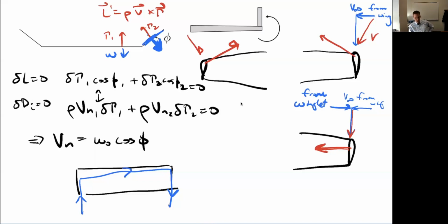So in other words, with this type of optimal loading, I've kind of increased the loading on the winglet such that it's not really getting any benefit, but it's generating more circulation that actually helps the wing. So overall, the winglet system, my entire wing, right, actually gets a net induced drag benefit, even though the winglet is not really generating a component of thrust. It's really better, rather than trying to use the wing to help the winglet, to use the winglet to help the wing, which kind of makes sense, right?